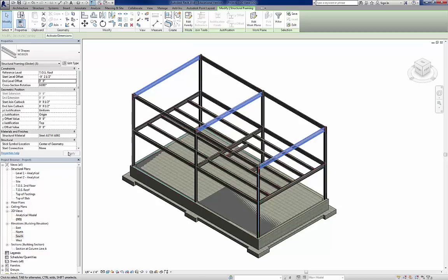You hit apply, you'll see that'll tilt the beams down. And our end level is going to be negative 2.5 inches as well. The reason we're doing that is we're allowing room for the pan to sit in here on top of them, so that when we pour the deck, it'll be even with the top of the beams.